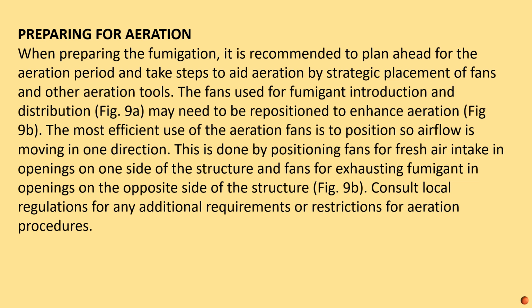The fans used for fumigant introduction and distribution, Figure 9A, may need to be repositioned to enhance aeration, Figure 9B. The most efficient use of the aeration fans is to position them so airflow is moving in one direction. This is done by positioning fans for fresh air intake in openings on one side of the structure and fans for exhausting fumigant in openings on the opposite side of the structure, Figure 9B. Consult local regulations for any additional requirements or restrictions for aeration procedures.